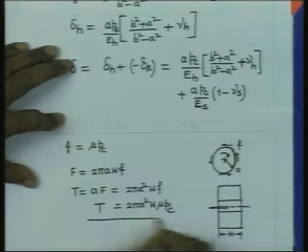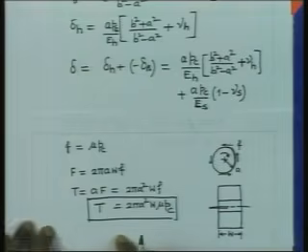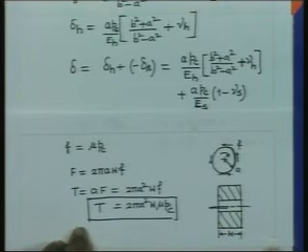So, this is really the formula for calculating the torque capacity of a shaft and hub assembly. If you wanted to see the section, this is how you will have. Finally, to sum up, the torque is given by 2 pi A square W mu into Pc, wherein the dimensions are: A is the shaft radius, mu is the friction coefficient, W is the width of the gear hub, and Pc is the contact pressure.